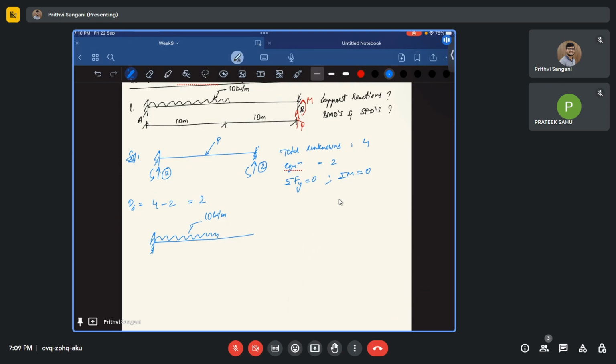So this will be a cantilever beam. Now I have converted this fixed beam to a determinate beam, which is a cantilever. Plus, now I'll add P in this direction, this is my unknown P. Plus, I also have M, which is unknown. Fine, we have done this. But what is the purpose of doing this? Let me name this beam A, B.